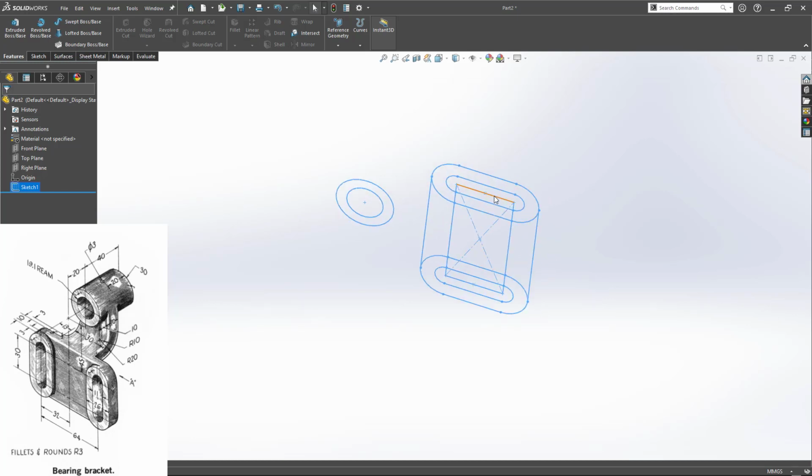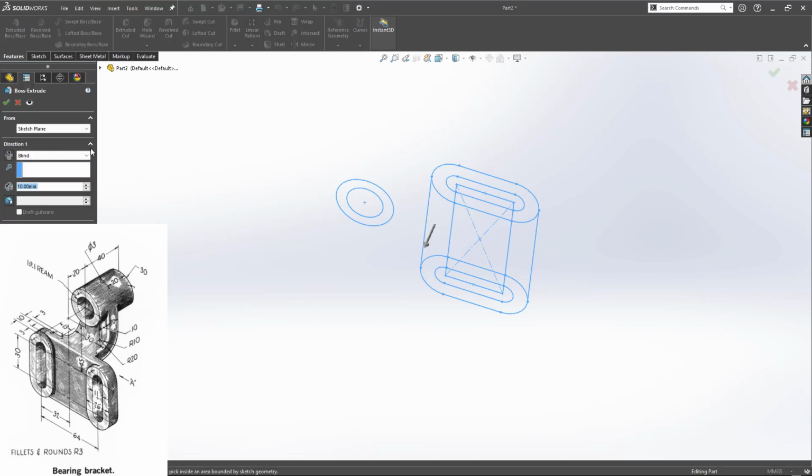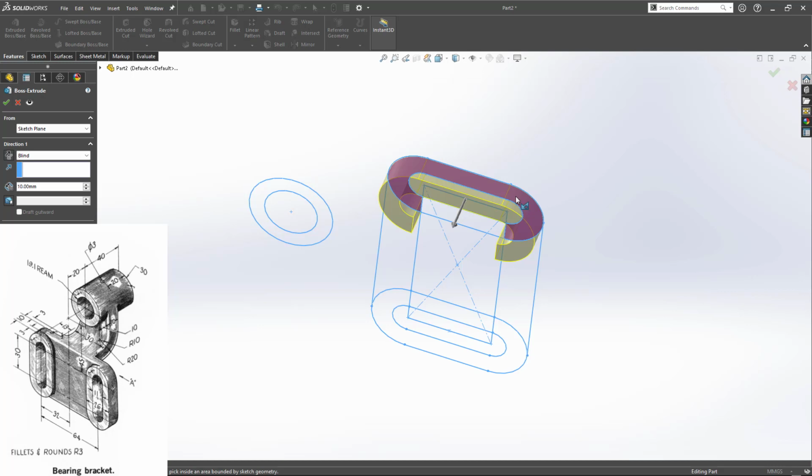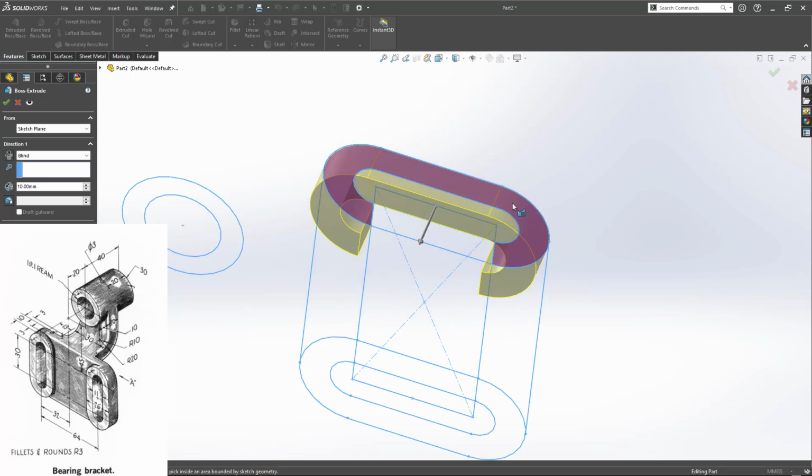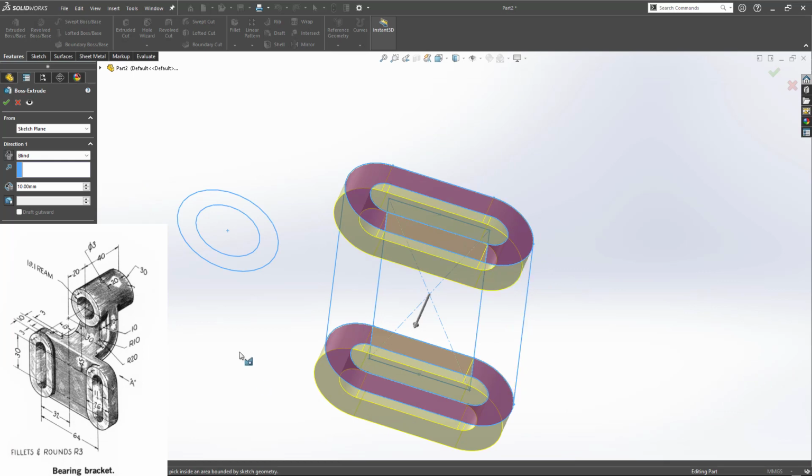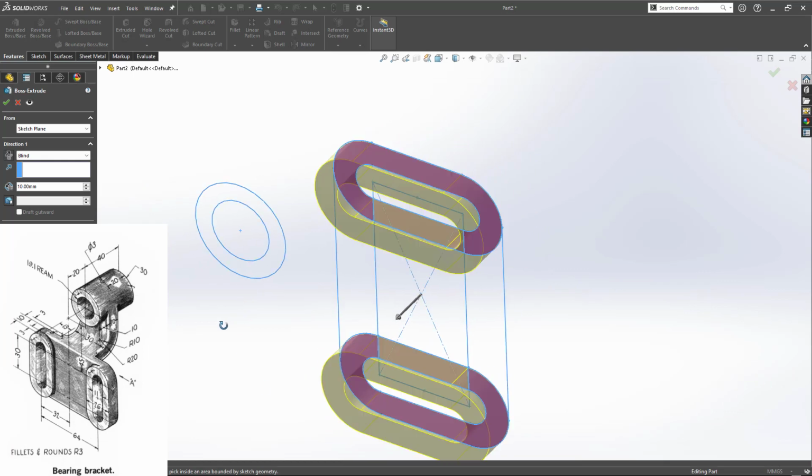So I'd like to go ahead with the extrude, and then this feature, not this one, only the outside one. Let us do one thing. We'll completely extrude this up to 10 mm as they have given. Correct? It's already 10, right?